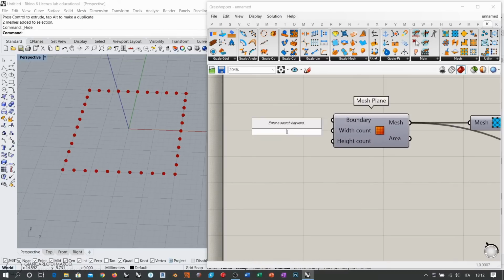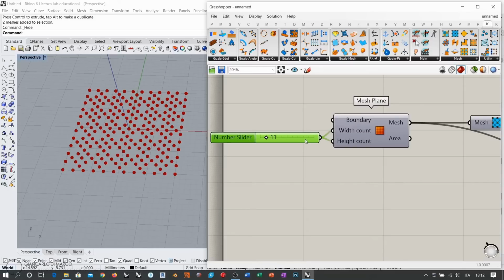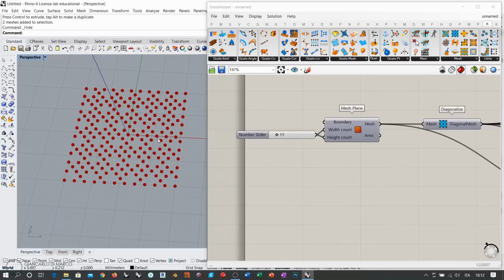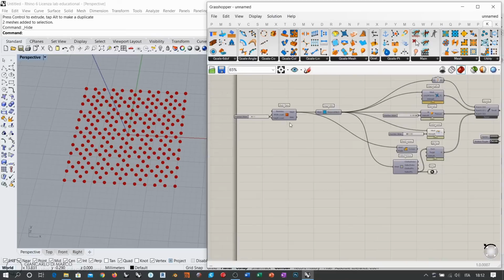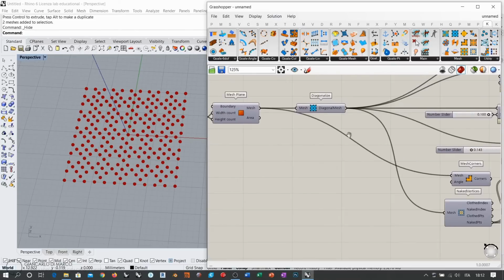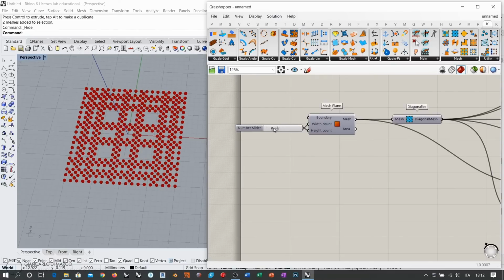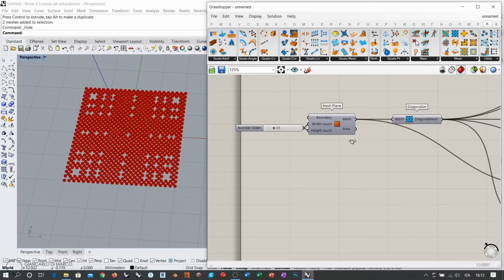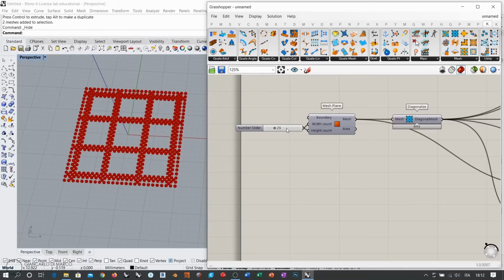So you might want to, for example, increase the resolution of this and try to work with more vertices, and then you see that this is actually emitting points that are not necessarily the naked points. Naked points are only the points along the edges of the mesh, but when you change this value here, this component just starts to work badly, as you can see.